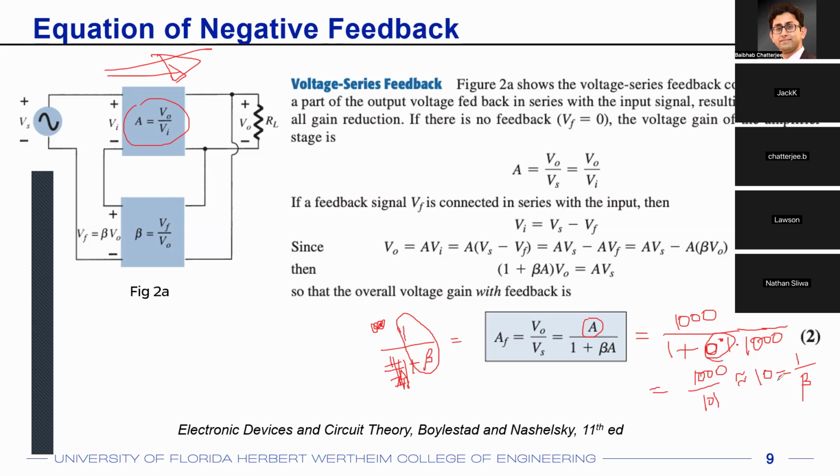Why is that helpful? Why is that important? Again, the gain A in a feed forward path can be implemented with, for example, an op-amp. Let's say an ideal op-amp or maybe a very high gain op-amp that you can buy from the market. Now when you buy an open loop op-amp, even if they say the gain is 10,000, when you measure it, you might find a gain of 5,000, or 11,000, or 15,000. Even if they mention the gain would be around 10,000, it will move around a lot. That movement happens because of manufacturing variations. Whenever you're manufacturing an op-amp or any kind of electronic system, you cannot manufacture it to an accurate degree so that the value always remains constant. So instead of 10,000, the value might be 5,000 or 11,000 or 8,000 or 9,000.